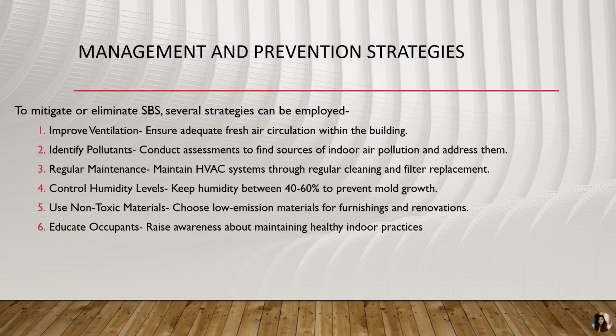Generally, we require proper ventilation, adequate fresh air circulation within the building, identifying pollutants, what are the different types of indoor pollutants, and trying to address them. We can use low VOC elements in the buildings, remove pollutants by having indoor plants, so that it maintains the indoor climate, making the indoor environment more pleasant and calm.